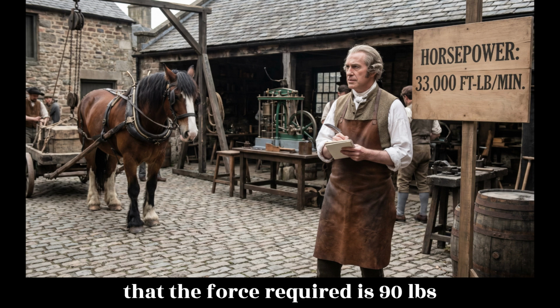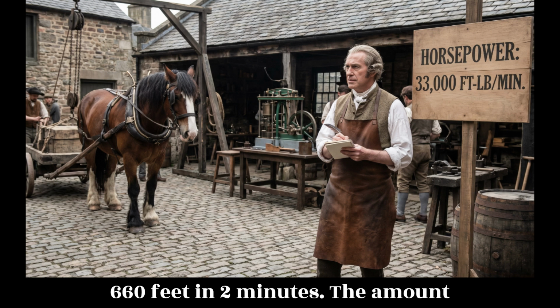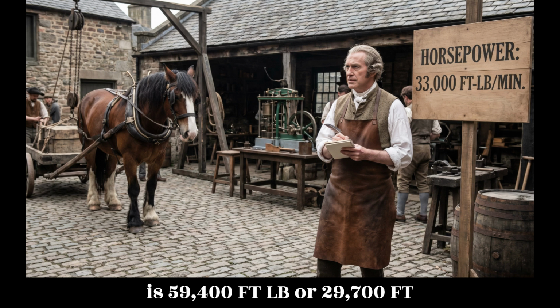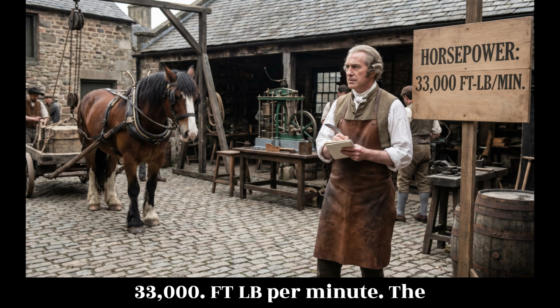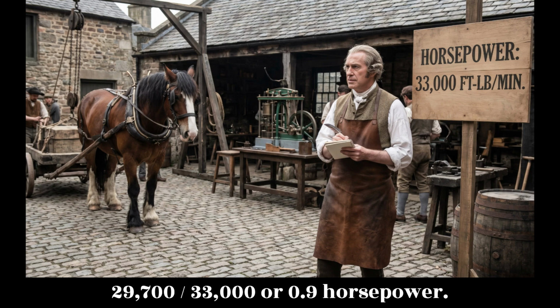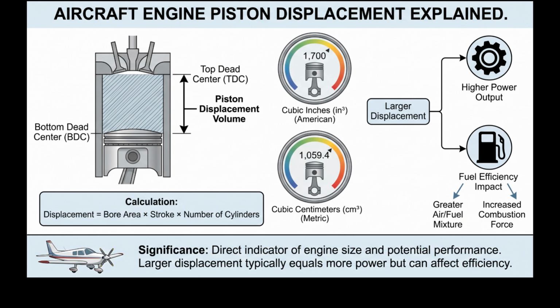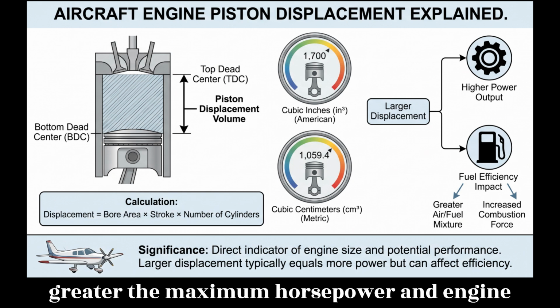Assume that the force required is 90 pounds, and the 100-pound weight is dragged 660 feet in 2 minutes. The amount of work performed in the 2 minutes is 59,400 FT-LB, or 29,700 FT-LB per minute. Since 1 horsepower is 33,000 FT-LB per minute, the HP expended in this case is 29,700 divided by 33,000, or 0.9 horsepower.